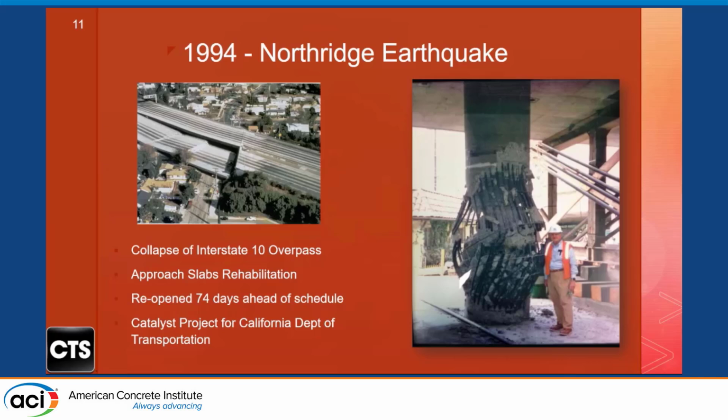And then another emergency, 1994 in California, the Northridge earthquake. That damaged a lot of overpasses, and the reconstruction was going to take a lot of time, especially because the approach slabs were damaged, so in order to reach the damaged overpass segments, they needed the approach slabs. Rapid Set BCSA cement was used to rehabilitate the approach slabs, and in fact, they were able to open to traffic the next morning so they could reach those overpasses. And overall, the project finished 72 days before schedule.